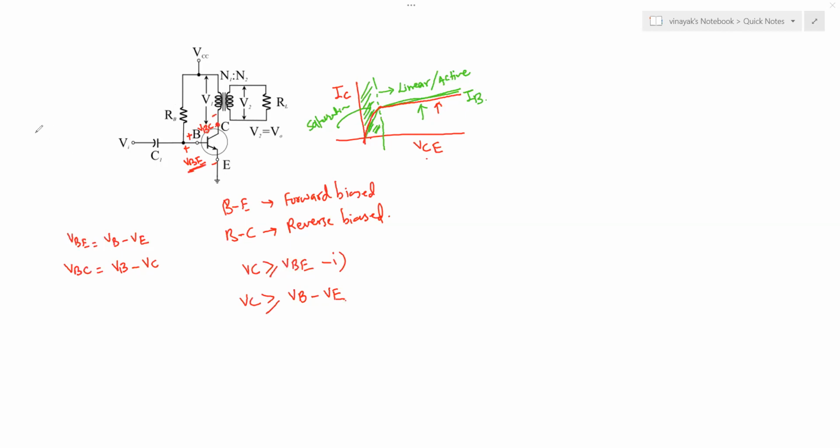So you use the resistor RB to provide the biasing to the transistor. This is the voltage supply VCC from which you draw the current I, and that current I flows through the resistor RB and provides the voltage at the base terminal, and that voltage must be greater than 0.65 to 0.7 volt for the silicon transistor. So VBE should be greater than or equal to 0.65 to 0.75 volt for the silicon BJT.